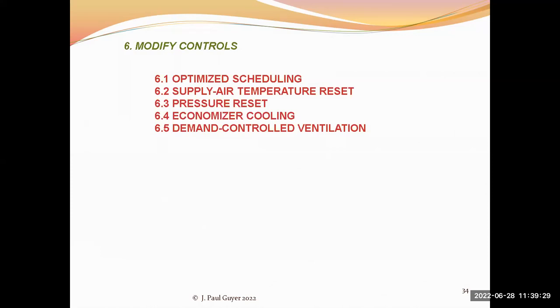And that takes energy. So if you can control that quantity of outside air that is brought into the building for ventilation purposes using these air quality demand control systems that are now on the market, you're going to save energy there. So that's an opportunity.